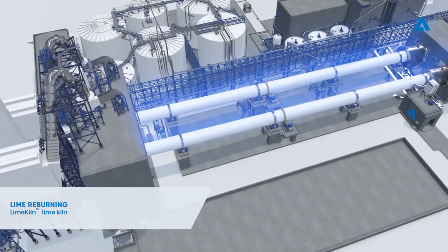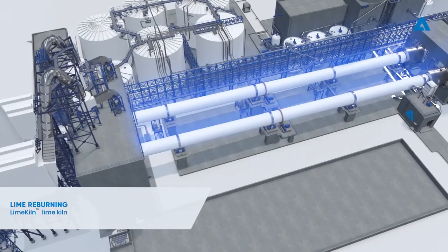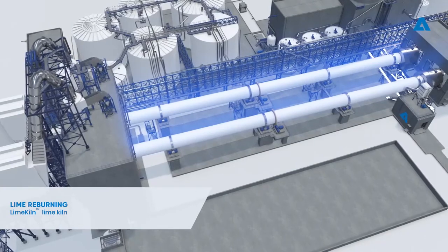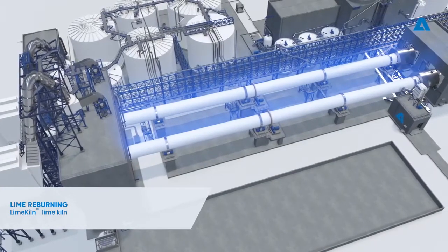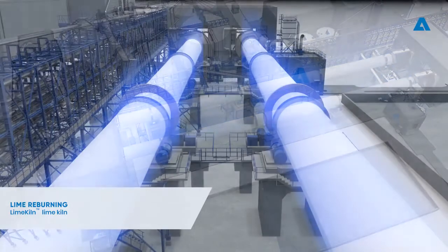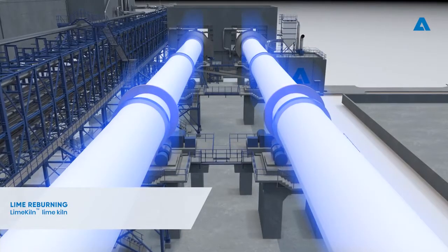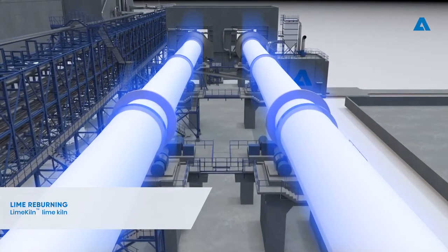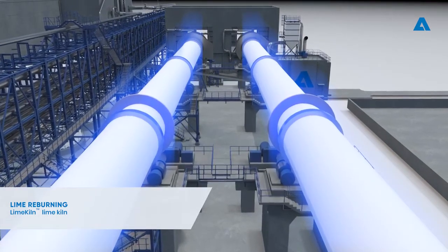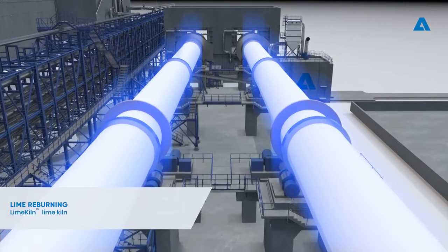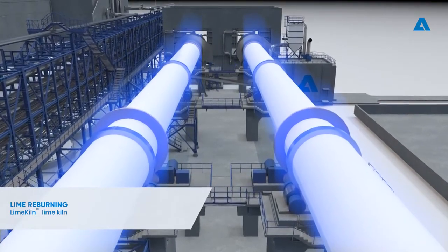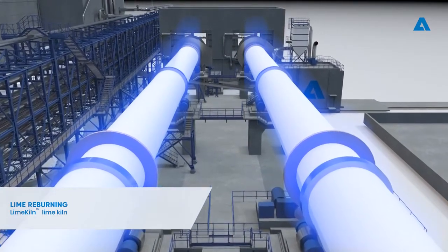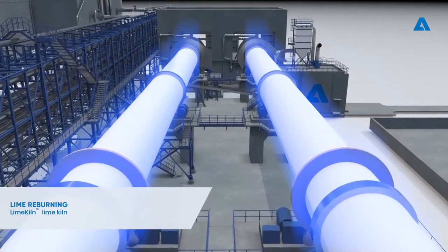Dissociation of lime mud to calcium oxide and carbon dioxide commences at a temperature over 850 degrees Celsius. The reaction is greatly accelerated when the temperature rises. To obtain proper reaction speed, reburning is carried out at approximately 1100 degrees Celsius. The objective of the lime reburning is to obtain homogeneous and porous lime with low residual carbonate, which will slake easily, and the resulting lime mud can be easily separated from the white liquor.